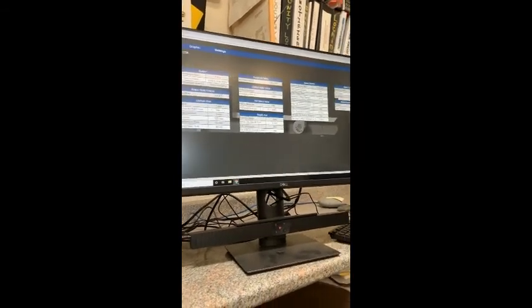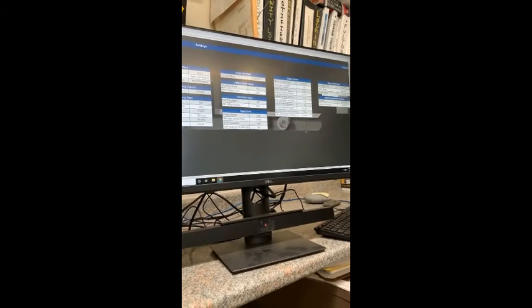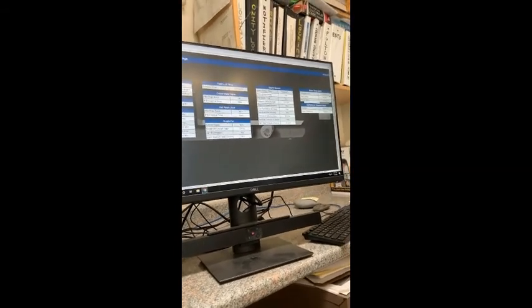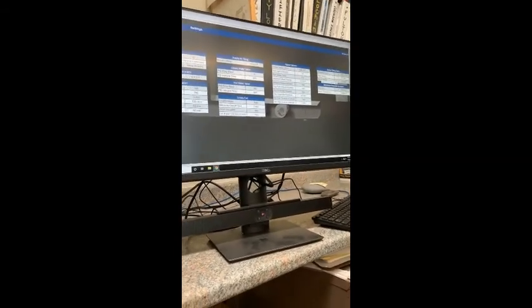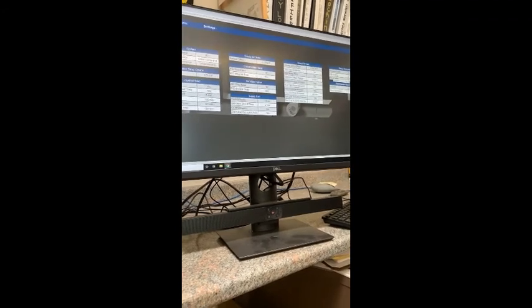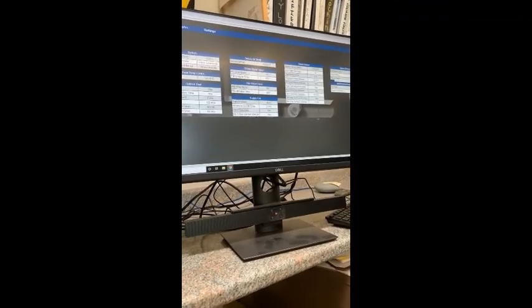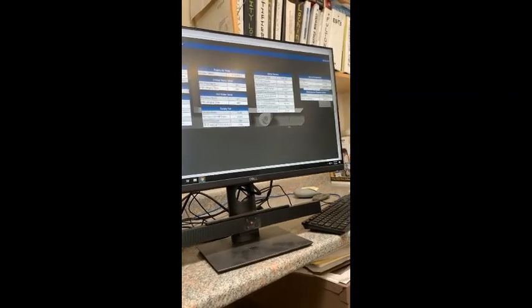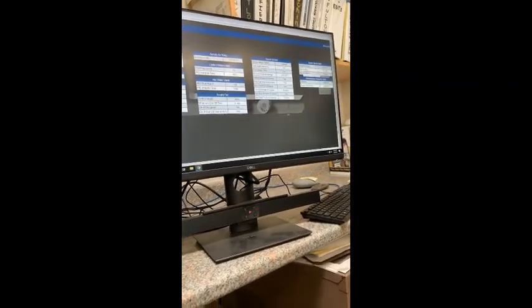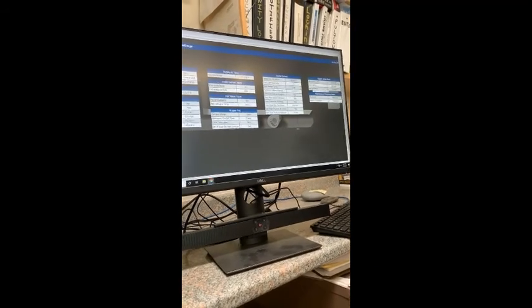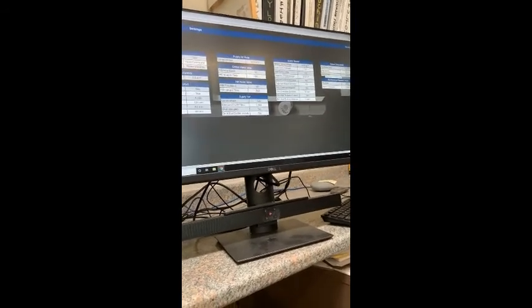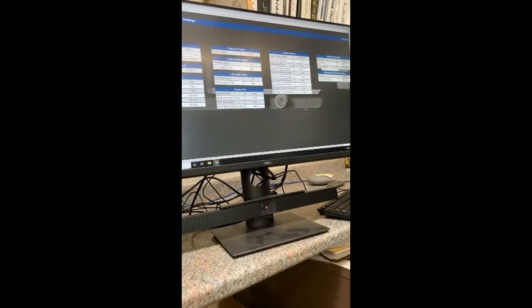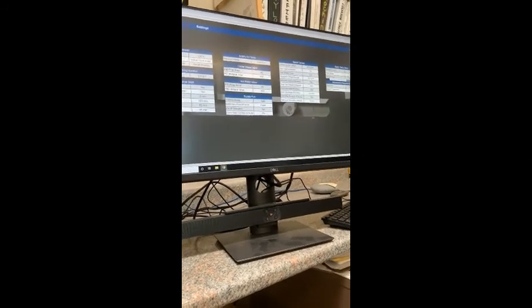So with the fan status, it would actually know if that fan motor's not working. Yeah, and it would send an alarm. If we're telling the fan to run and it doesn't respond within a certain amount of time, it would shoot an alarm saying, "Hey, this fan is not working." Because I've seen some old systems where it's still on the computer, it's still spinning, but it's not actually working. Yeah.